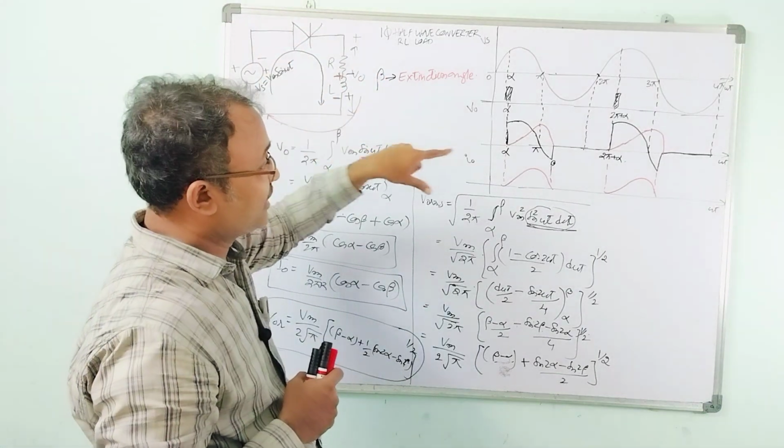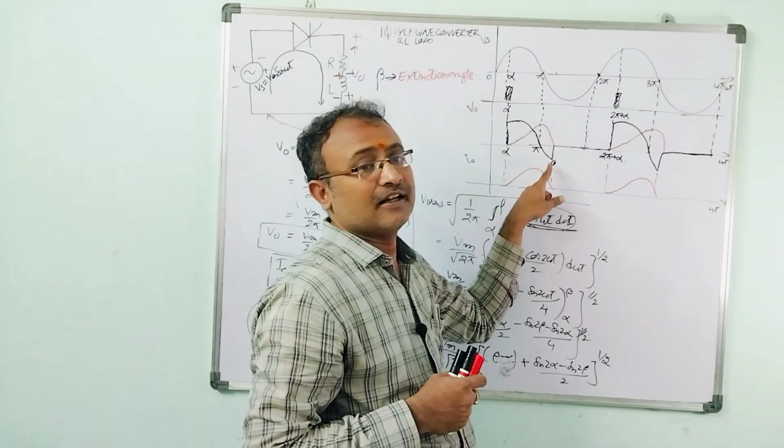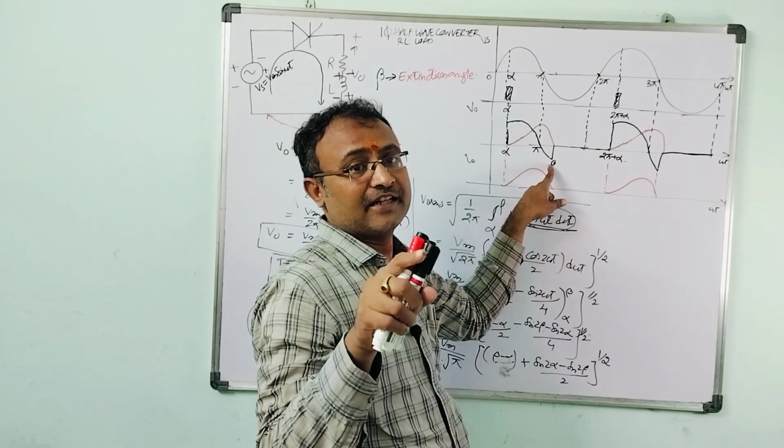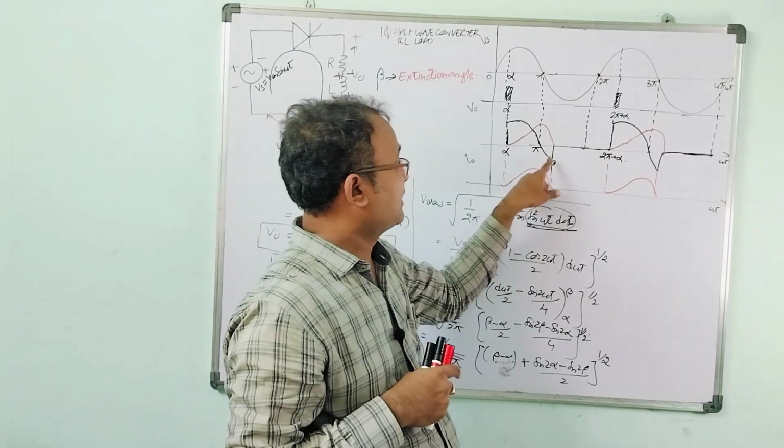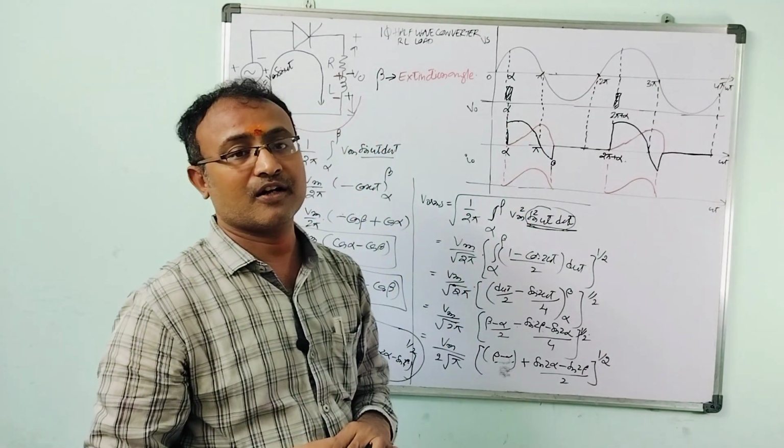It will continue till the extinction angle, when the energy in the inductor completely becomes 0, and then the thyristor goes to the off state.